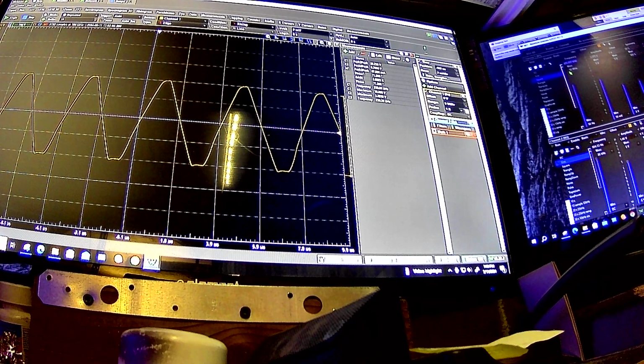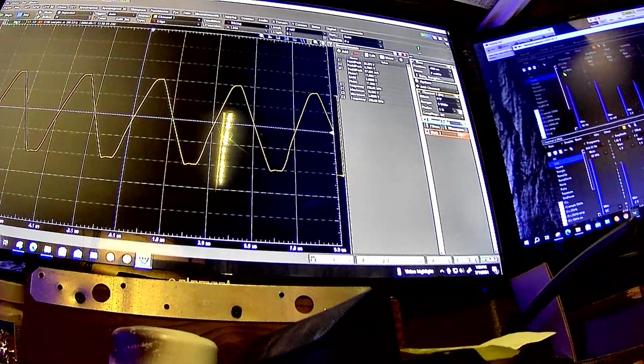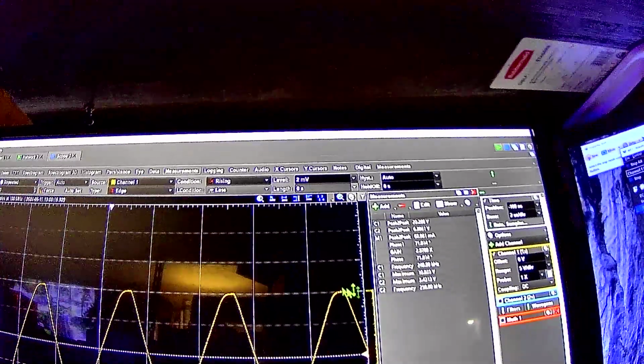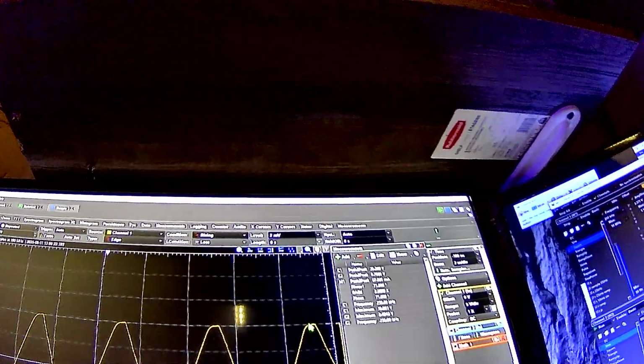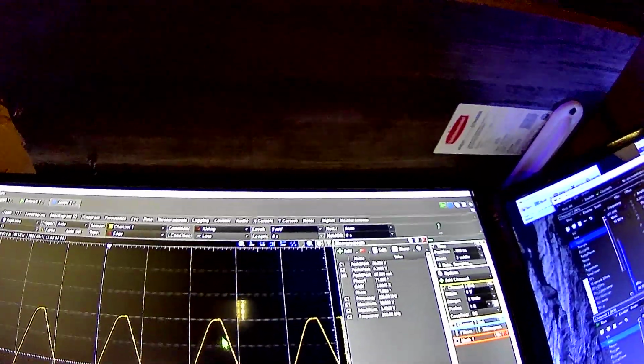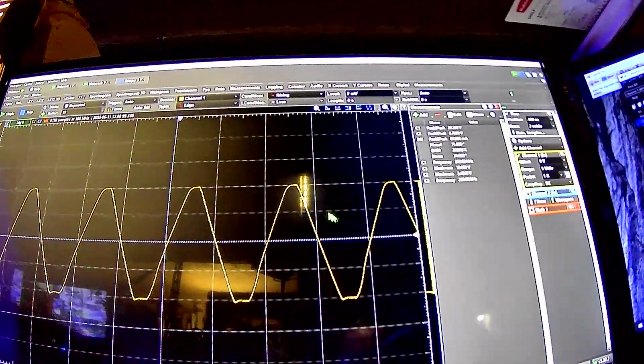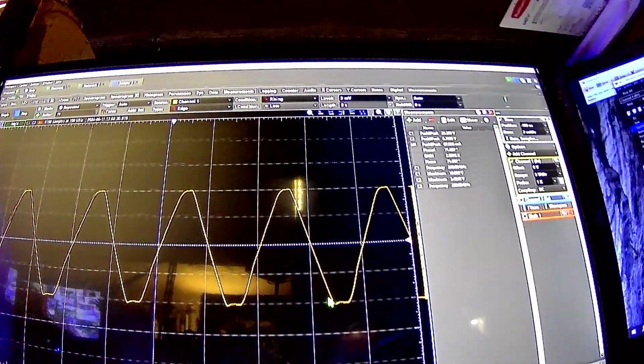Let me make it exactly. Okay, so I have it set to exactly a 250 kilohertz square wave, and that's what you're going to look at. That's the maximum output a DAC could actually generate, going from essentially 1 to 0 to 1 to 0, even though this waveform actually has a lot more points than that. Still, it's slew rate limited.